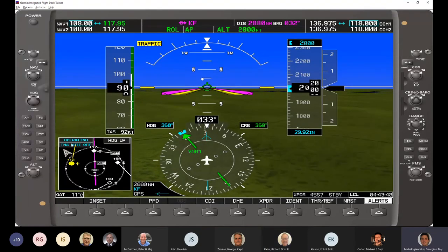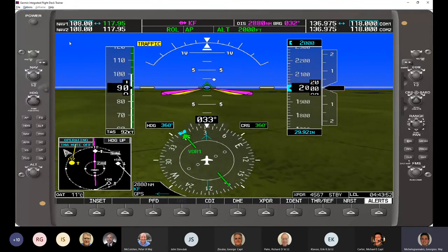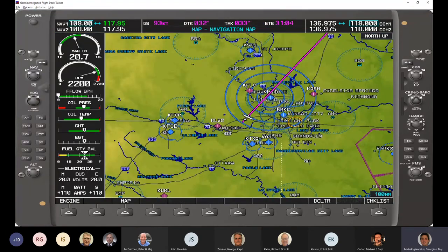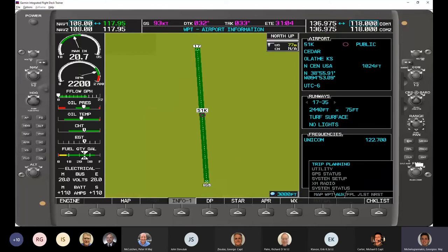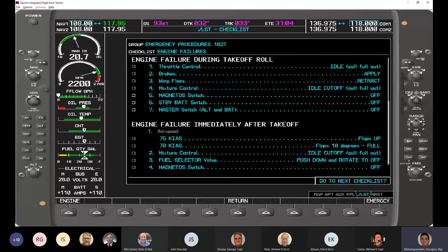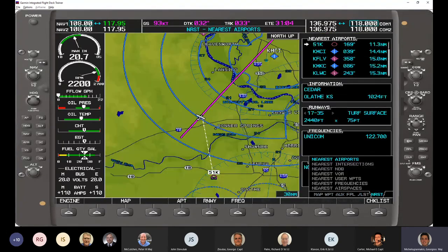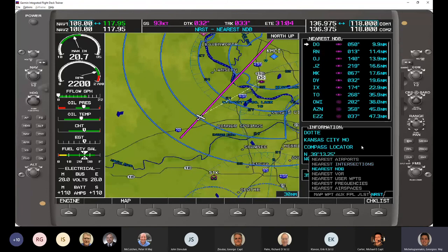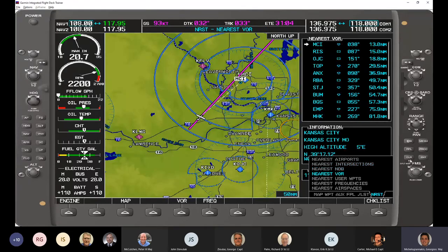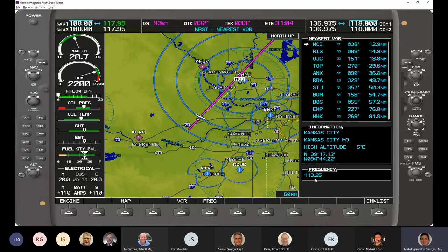Okay, let me also demonstrate. Oh, I said Romo. Yeah. Okay, so we'll go to MFD. We'll go to our nearest VOR because I want to find a frequency. We're somewhere in Kansas. I don't know the VORs there. And let's see, nearest VOR. Kansas City MO. What's it? 113.25.